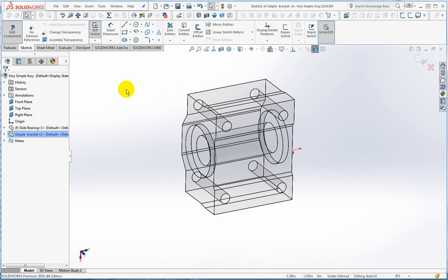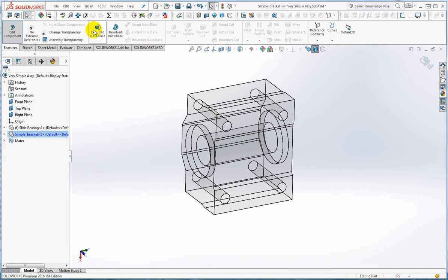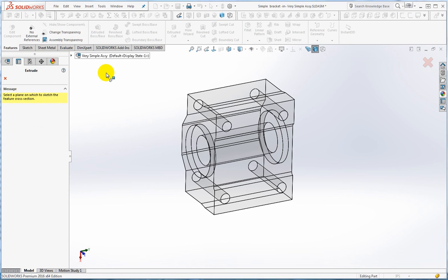If you look at the context, you'll see that we are currently in a sketch. The first thing SolidWorks does when you do this action is to create a part and to start a sketch. If you want to have a sketch in a different plane after the fact, you can exit the sketch. In fact, that's what I'm going to do. Mainly because what I really want to do is to create a feature, which is an extruded boss base. I'm going to be using the same plane as before, but by clicking on Feature Extruded Boss Base, it will do a two-step. It will create a sketch, and after the sketch is saved, it will then ask me for information on the extrusion. So it's kind of a nice shorthand.